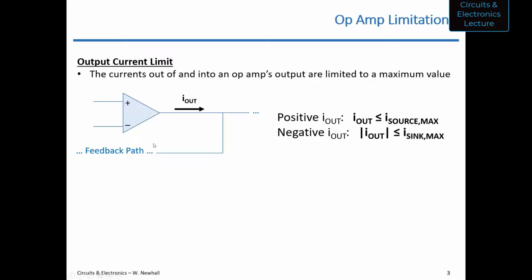Well, you'll find, and again, we'll cover this later in lab, if you use in the K ohm range, you'll have milliamps in your feedback path. If you use ohms, your feedback path would try to have amps, right? You don't want to do that because these op amps can only have maybe a few milliamps, maybe up to 50 or 100 milliamps coming out. So if you try to have an amp go through your feedback path, it's not going to work. We'll cover more on that in lab. But I wanted to put this into context, why we care about this.